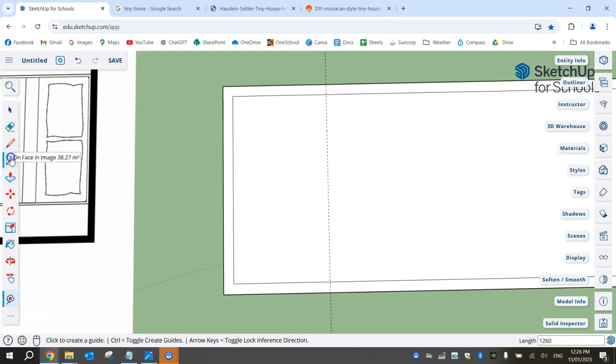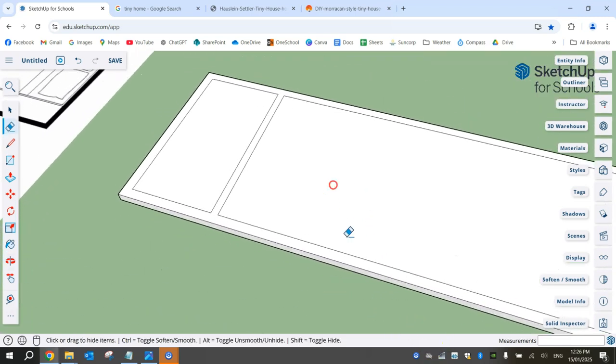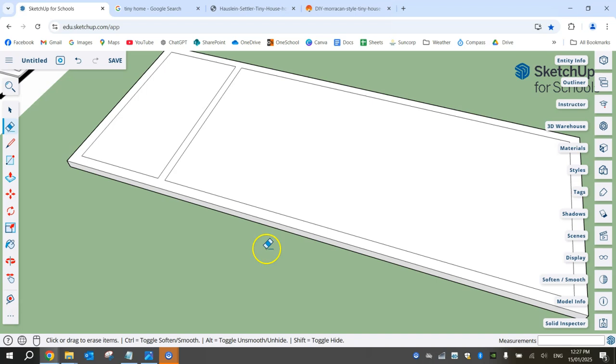So I can now grab a rectangle tool, simply click in that intersection there and drag down to the bottom line here. Now it needs to be 90 millimeters width, and I can see it's 2155 millimeters in height. So I'm going to write 90, 2155, and press enter. Okay, I've now got my wall in there. If I wanted to, I could press the E for the eraser, just erase some little lines there. Okay, and that means all walls are connected now. I might just erase that guide as well. And there we have it. We are ready to create our walls.